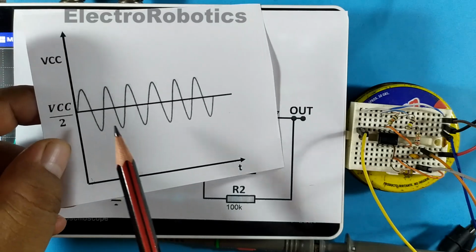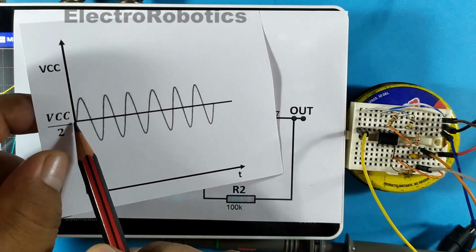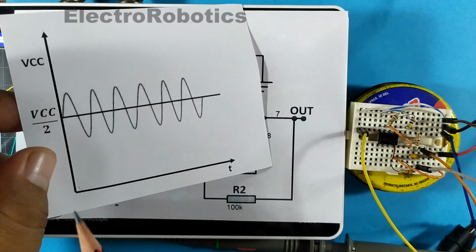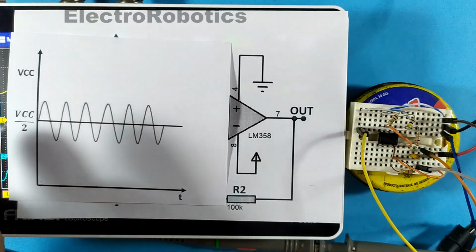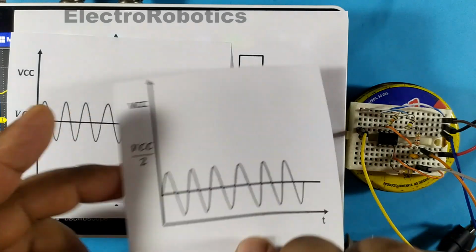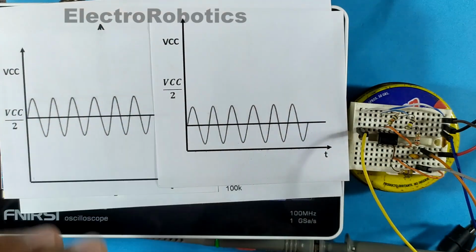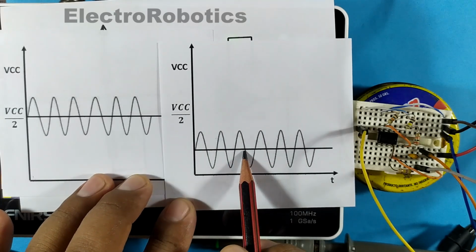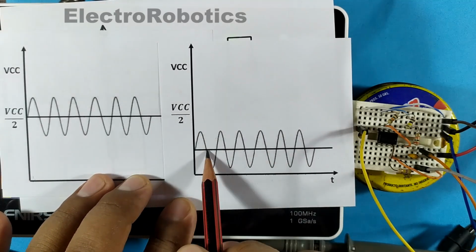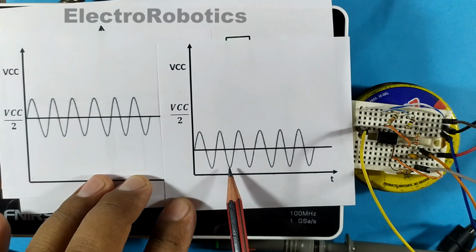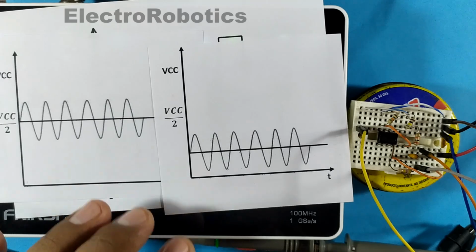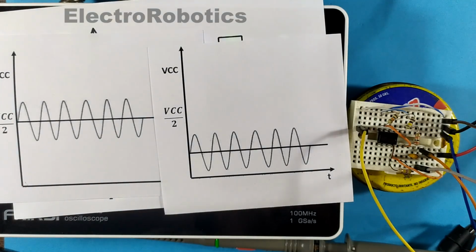So what I have to do is first reduce this midpoint, lower it as much as possible to 0 volts, so that this signal is like this signal. In that way, so what we do is lower it from the middle to as close as possible so that the valley of the signal reaches 0 volts. So that when amplifying it, the signal is much better. And how do we do that? Well, using a voltage divider.